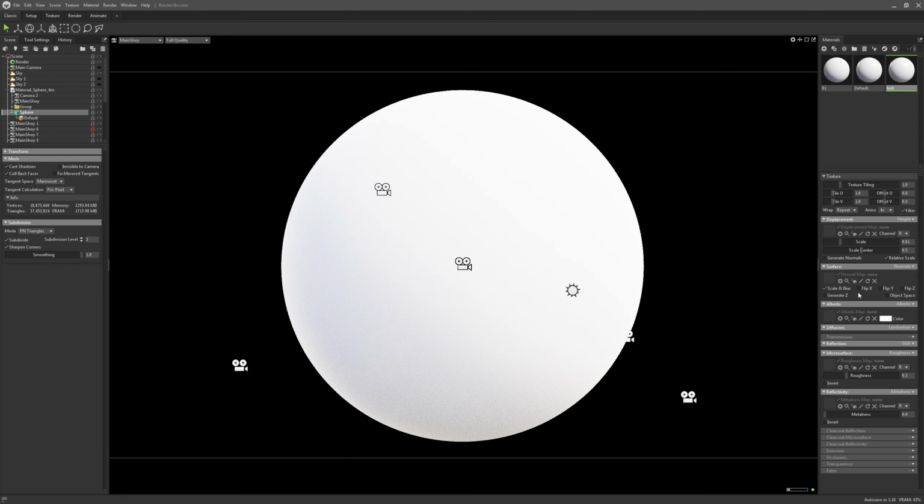Now my normal map seems alright, my albedo seems alright because I can use both of them, but now let's go to reflection and change it to microsurface, and make sure that this is set to roughness as it is, instead of glossiness. We need to be referencing the red channel, of course. And here we have our metalness, which we are not going to be using, so in this case it should be 0. And we're going to go to occlusion and set this to occlusion as well. Now we have all our inputs for the material.